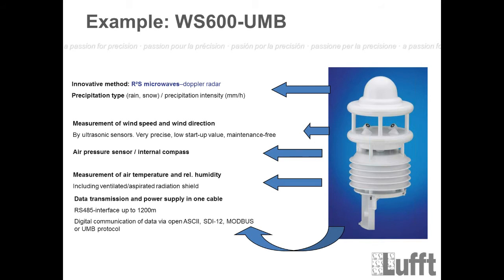So it's clear that if you install a sensor, you have to check our installation guides, because normally in a diameter of 10 meters around the sensor there should be no plants and nothing which will move, right? So that the sensor can really only detect the precipitation. That's very important. Another important thing is the sensor itself is heated.